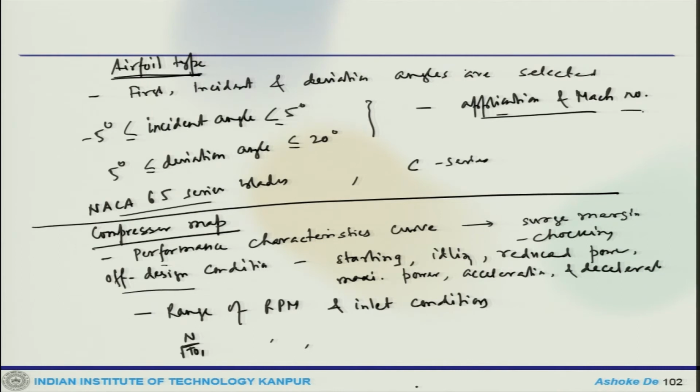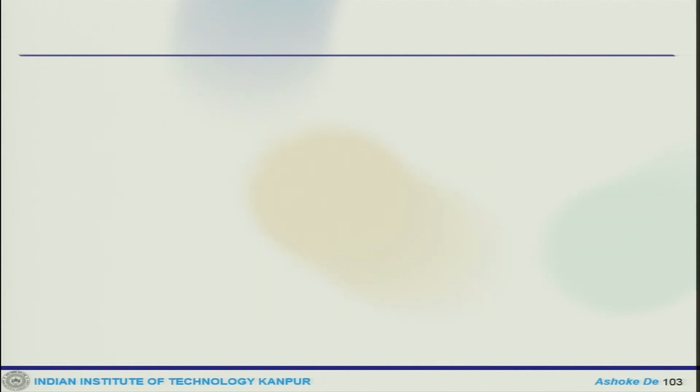And then you have the surge point which occurs before the constant speed curves reach a maximum value, and stage characteristics are similar to overall characteristics, but with much lower pressure ratio. And for axial flow compressor, since the axial velocity is maintained constant, annulus area is inversely proportional to air density, thus the annulus area of the compressor decreases from front to rear stages, just to accommodate all the other characteristics.